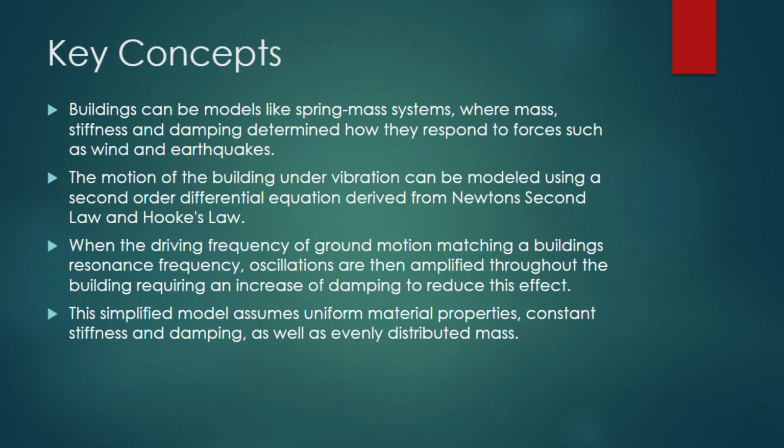Okay, so now this last slide here is kind of the foundation of everything that we were modeling. We are treating buildings like spring mass systems, which was a little awkward at first, but it actually worked out pretty well with skyscrapers. The idea is generally just that the building has mass, stiffness, and damping. And when something like an earthquake pushes on it, it reacts just as a spring would.